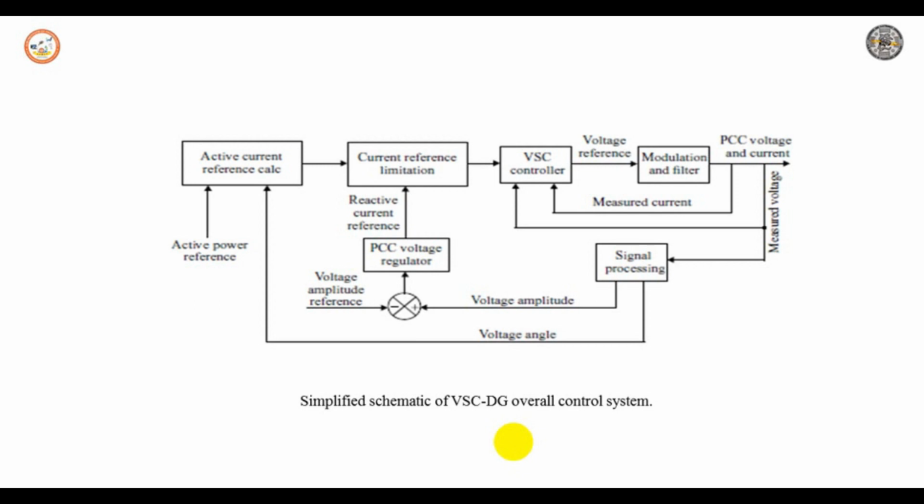If the voltage at PCC is reduced, then within the voltage regulation using DG, an injection of reactive power is needed. Assuming the current command for the converter moves to B implies an increase in amplitude above the allowed value. Since such operation is not possible, the current limitation protection may change the command to the current vector C.